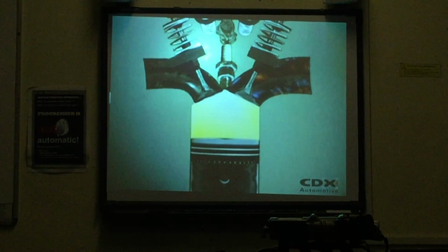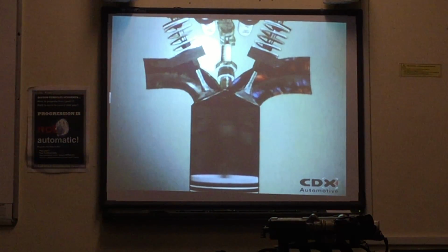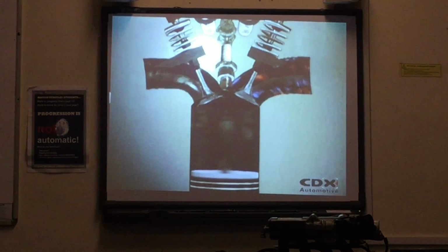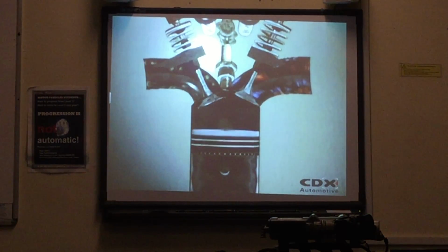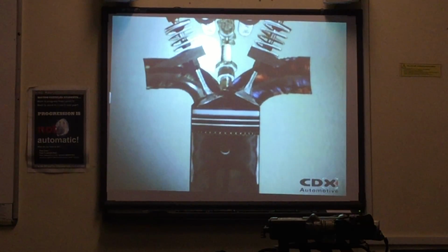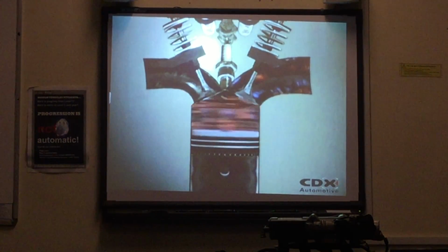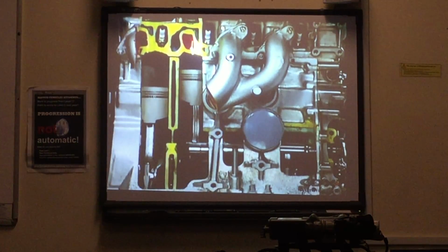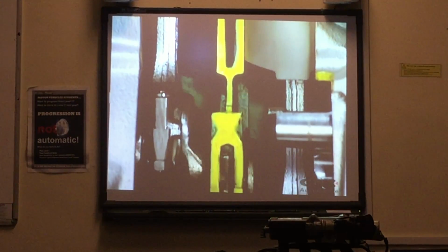The burning gases expand rapidly and push the piston down the cylinder until it reaches bottom dead center. The reciprocating action of the piston turns into the rotary motion of the crankshaft. The crankshaft forces the piston back up the cylinder, pushing leftover gases out past an exhaust valve. And everything is back where it started, ready to repeat the whole process. The whole process is a cycle. A new mixture enters and is ignited. Combustion occurs, expanding gases drive the piston down and turn the crankshaft, which pushes the piston back up the cylinder.